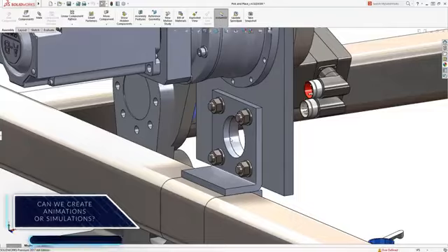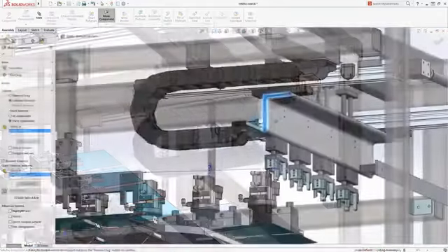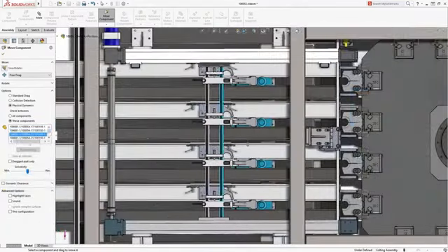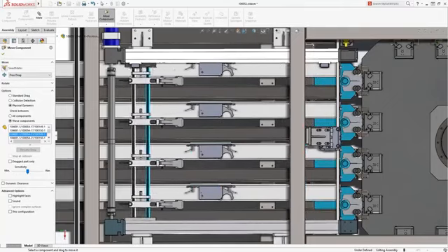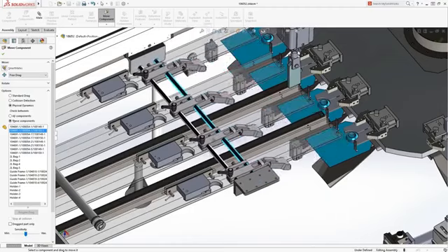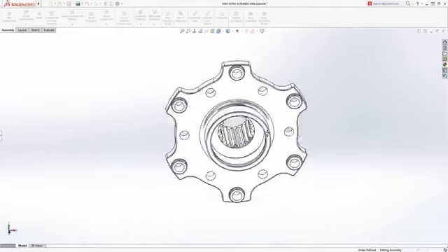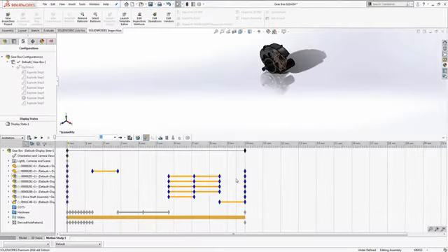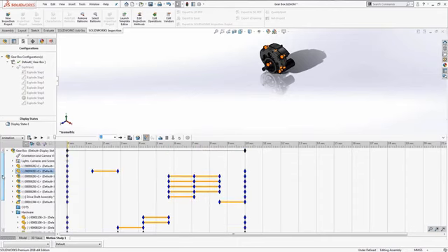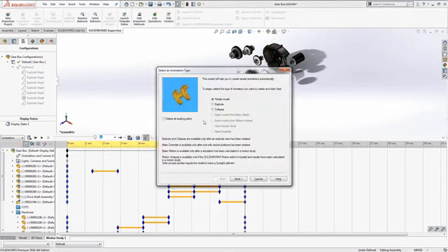Animations and simulations. You can create animations and realistic simulations with both SolidWorks and FreeCAD. In SolidWorks, you can create animations by dragging the time bar along the timeline to a specific point you choose, and then drag the component you want to create animation with to a target location. The Motion Manager moves the component from its initial position to the position you designed at a specific time. You can use the Animation Assist to create animations or to add rotation, bursts, and gathering of existing animations.